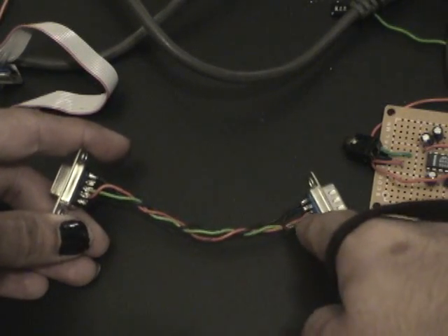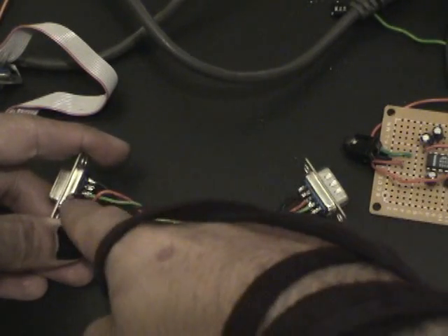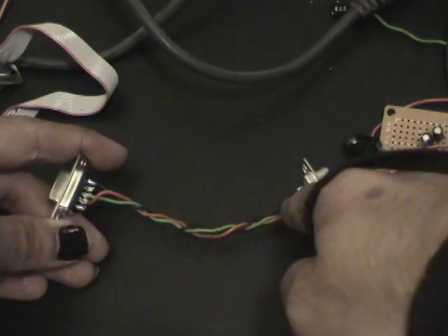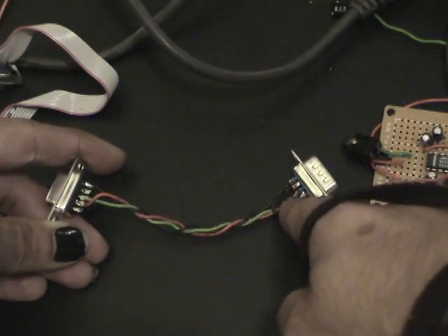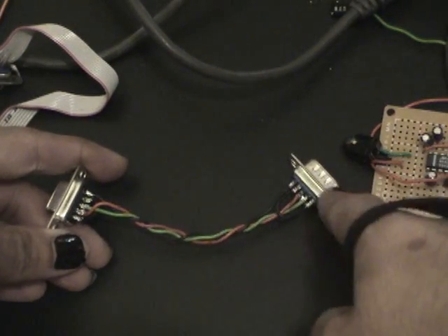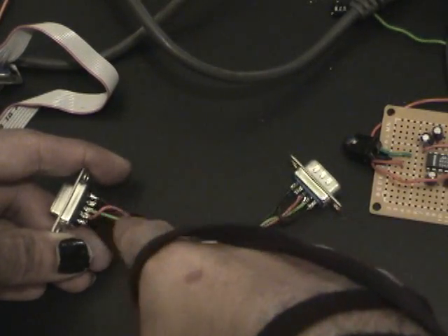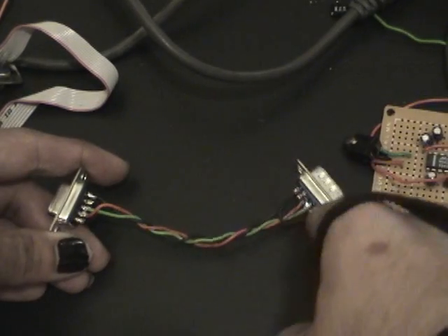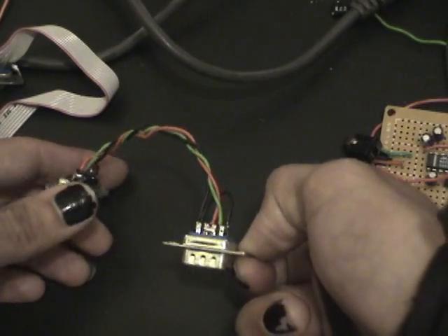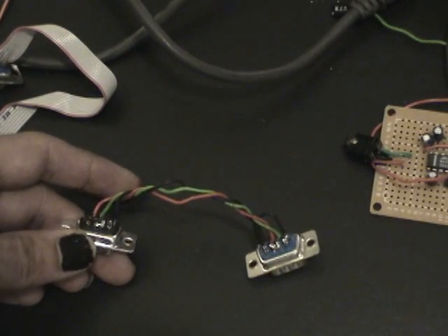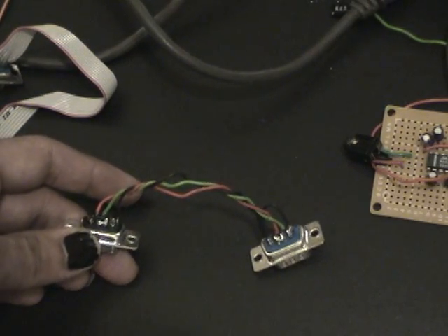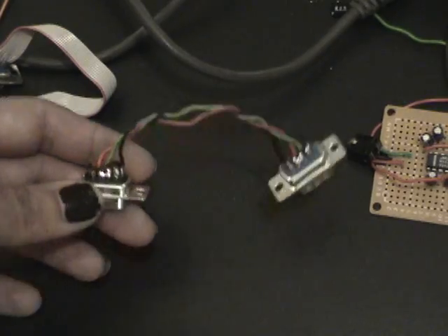is actually leading to the receive over here. So this is receive on this end, is transmit over here, and transmit over here is actually receive over here. So you're literally just crossing the transmit and receive lines, as well as this black wire, which is common ground. We're jumpering the appropriate pins on the actual connector itself, so the data terminal equipment itself thinks that the machine on the other end is actually up and ready to go.